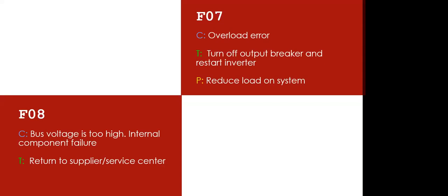F08 might disappear if you restart the inverter. It might be sorted. But if it has taken too long, maybe the F08 has been there a long time before we notice it, it might have turned into component failure, which will affect a section of the main board. If that is the case, we need to return the inverter to the service center for repair.